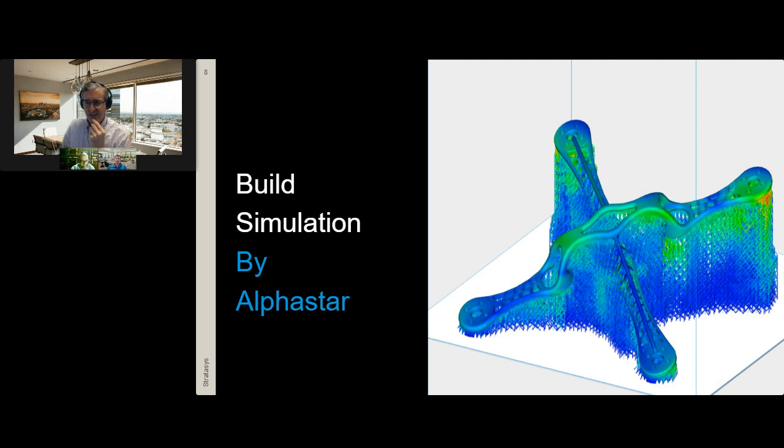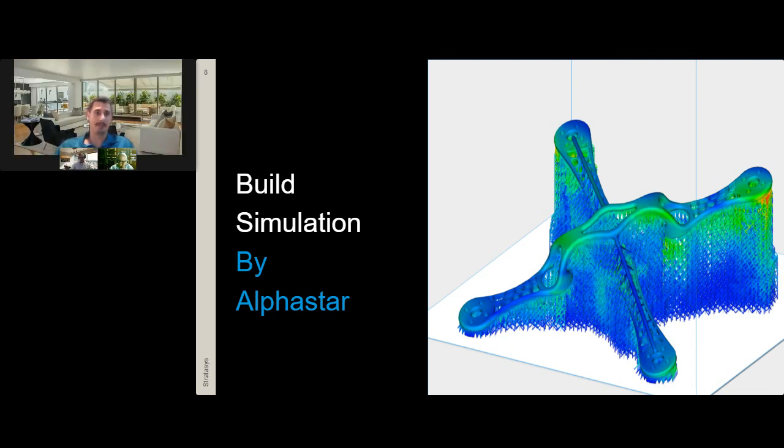Yeah, so as far as Accuracy Center, yes, you can use Insight. As far as the comparison tool, you're taking the scan and comparing it to the CAD model within GrabCAD Print. So the actual comparison and the plugin is only in GrabCAD Print. But if you want to process your part in Insight and build it using your company's parameters that you've deemed are the best, or just have the ability to control more things, you can absolutely build it in that software and then just do the comparison in the Accuracy Center.